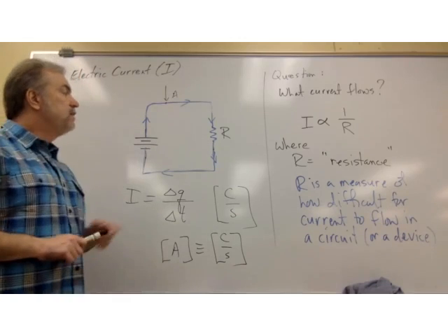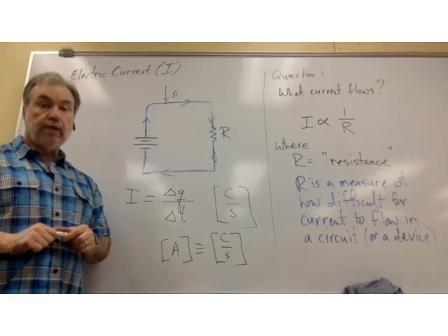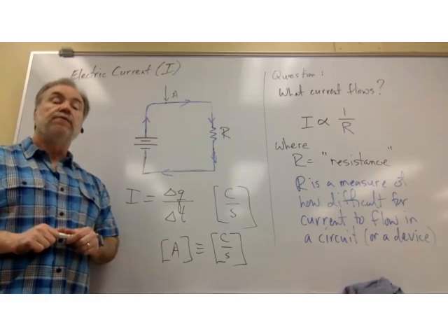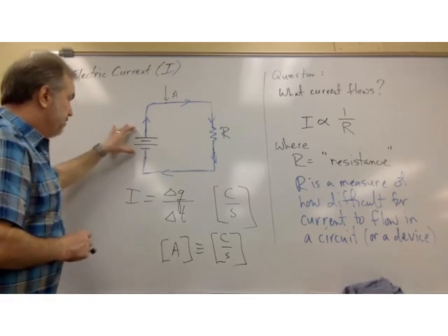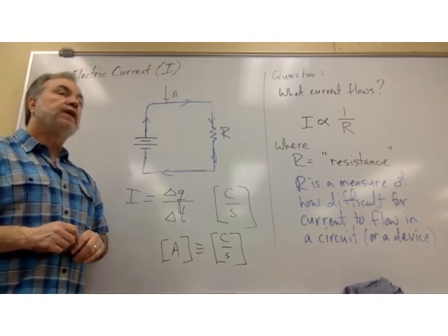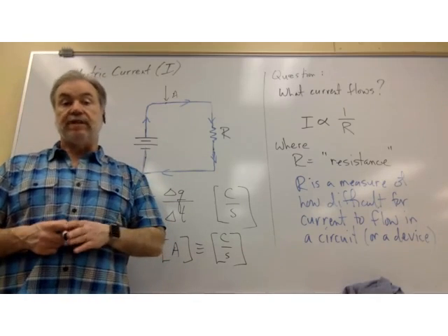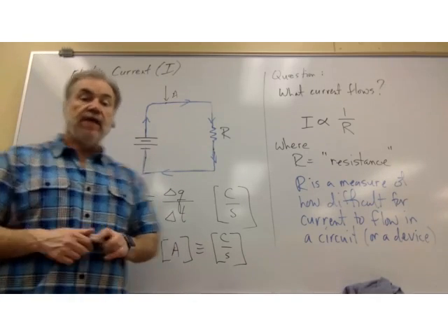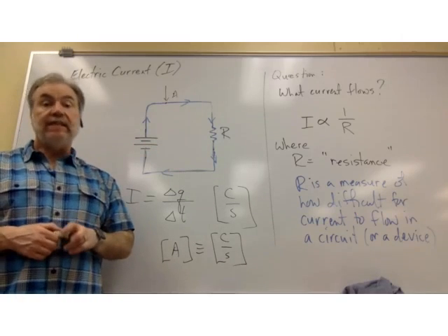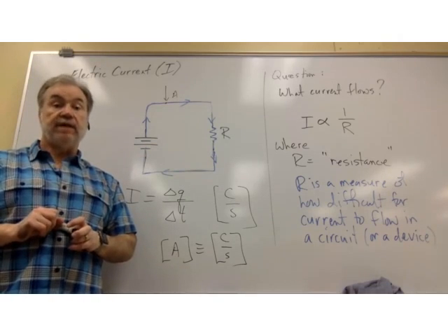So in fact, the battery itself, with its so-called internal resistance, is also going to inhibit the flow of charge. The battery itself actually decreases the amount of charge that flows, okay? And so the potential difference, the drive, the force, the electric field, however you want to think about it, that the battery gives to push charge around is actually slightly less than you might guess from the rating stamped on the side of the battery.